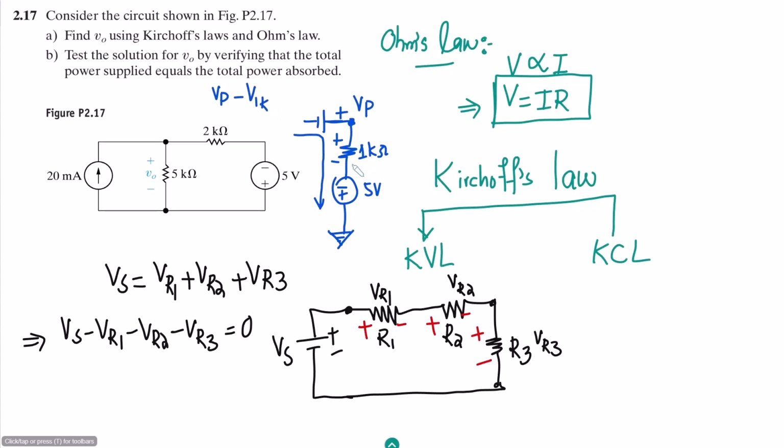This is the voltage across it, and here again you can see that the current is entering through negative and coming out of positive, so V5 is again a voltage drop. And this one is the ground, and it is always at 0 volts, so here let me use 0 volt and it will be equal to 0. We can always apply it to branches, to loops, to meshes, and anywhere you want. So this is the KVL.